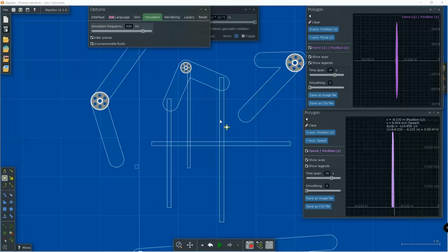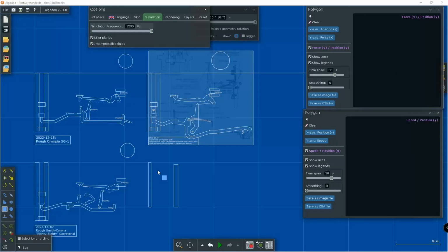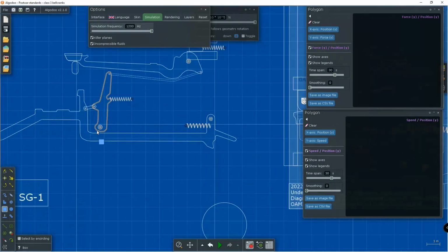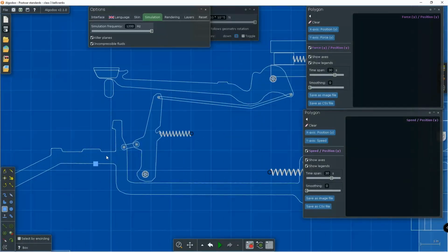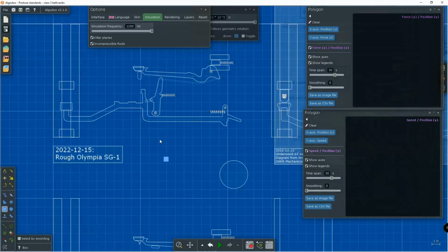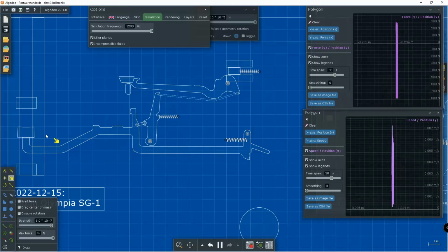Also, in the case that we have a Bellcrank-shaped rigid constraint between 3 points, but the effort and load are parallel, then I would be more reluctant to call this a Bellcrank and would rather call it a special case of lever where the kinematics of the effort and load vertices are different than on a conventional lever. With that, you can see that all these type actions make use of class 3 Bellcranks because of this pivot order and the respective direction of the effort vector being appropriate. And, of course, these key levers here are class 2.